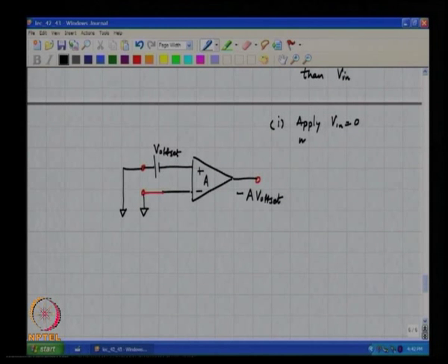You have seen that the output voltage of the op amp is always either going to be ground or VDD, because the gain is so high that it will saturate the internal nodes of the amplifier. Okay. So apply V in is 0, measure V out, from which you get V offset is not a good idea, because the amp will saturate.